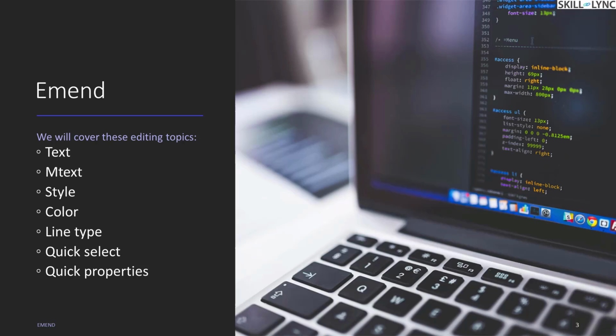And also regarding the properties, we'll look into the linetype property and how to apply it. Parallelly, when we operate on multiple textual objects, we need to edit the properties of each and every one of them. So we'll look into the methodology to select the required objects using a filter command called quick select, and also how to modify those properties in different manners.